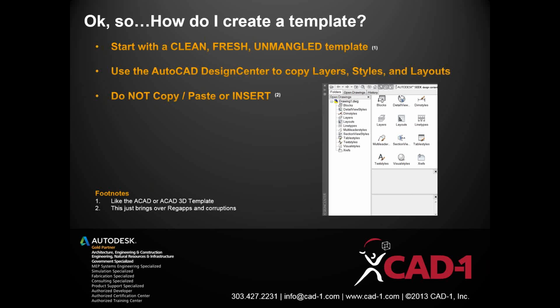There was a company who had a template, and they had brought pieces and parts of this template. Everything that I said not to do, this organization did, and their template was 10 megabytes in size. Their template had a couple of layouts, had some layers, 10 megabytes in size. Every time they started a new project using the template, within a day or two, that project became wildly unstable. And they were saying, AutoCAD sucks and it's awful. Well, we tracked it down to the template, 10 megabytes in size.